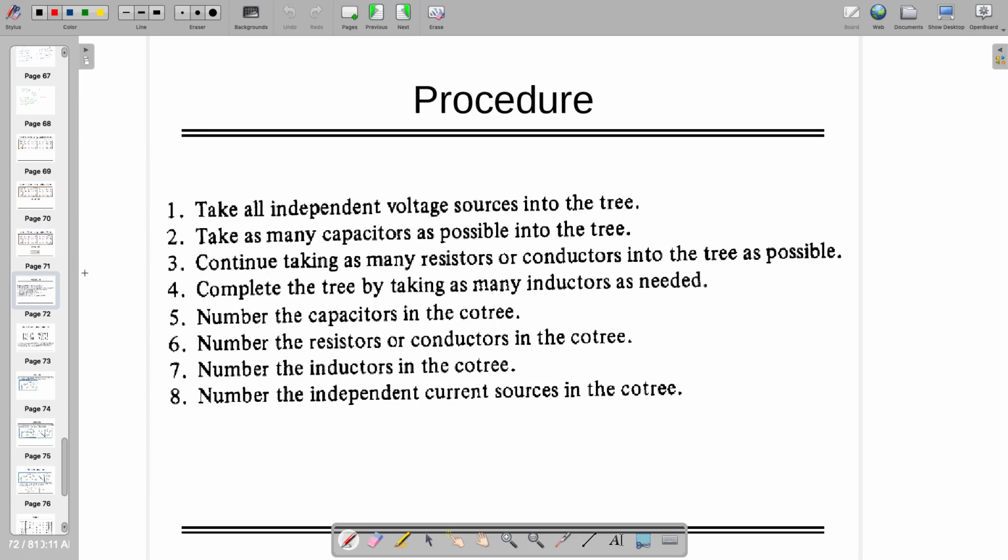So in state variable formulation, we understand what independent voltage sources are. All the function generators, power supplies, and all other things are actually independent voltage sources. They have to be on the tree. We know what a tree is, right? And all the people might take different trees, so the solution may be different. The final answer will be the same, but procedure-wise you may have a different tree. So we need to look at that.